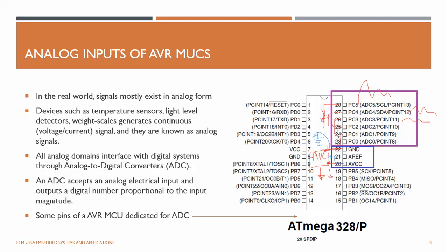You cannot do parallel computation because you have only one ADC converter. You don't have multiple ADC converters to run in parallel. So you can use one channel, do the ADC and stop it, and then select the other channel and do the ADC when you have multiple signals.